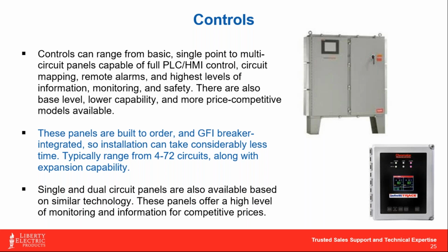So you can work off a standard 30 amp 2-pole breaker out of your main panel, let's say. The nice thing about these smaller 2-circuit panels is that they're much more affordable. They're small and compact.